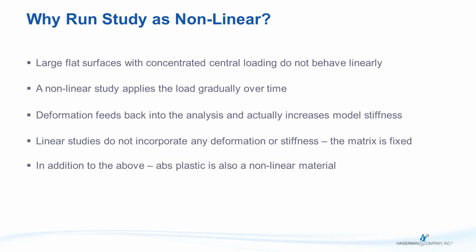So when we run a study, why do we run it as nonlinear? First and foremost, when you're dealing with a large flat surface and a concentrated load at the center of that surface, it is not going to behave in a linear fashion. It's going to have some nonlinear behaviors to it as it deforms and stretches.